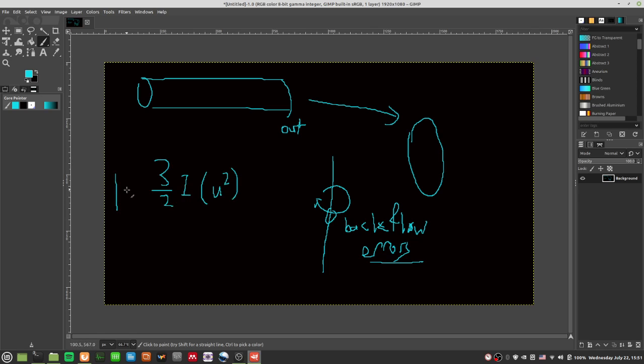you have this from the RANS case. From RANS, you have your inlet turbulent kinetic energy calculated like that. For LES, you can do 0.2 times 3 over 2 I times U squared.